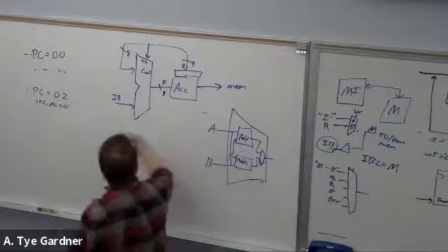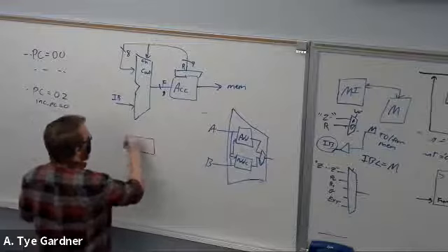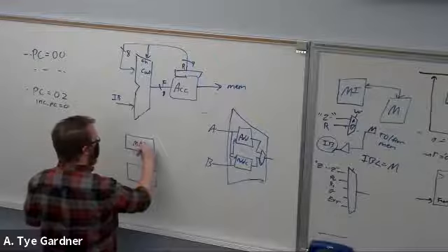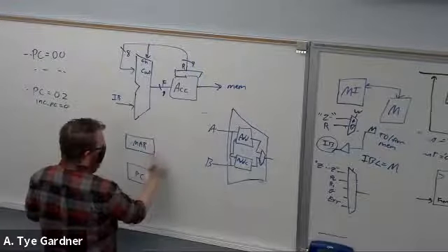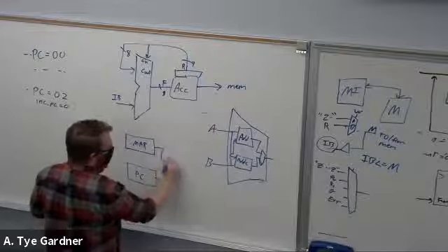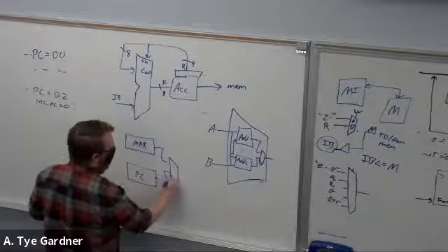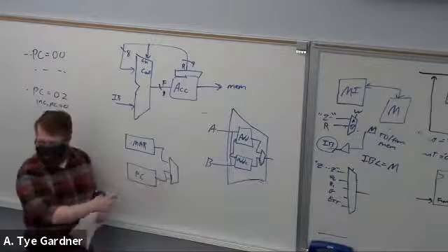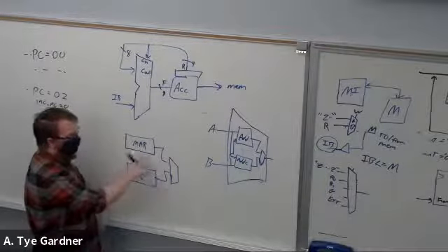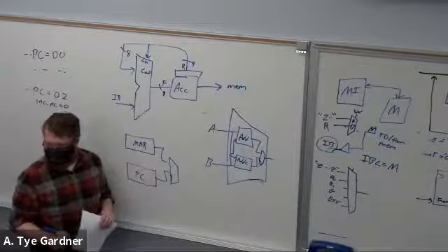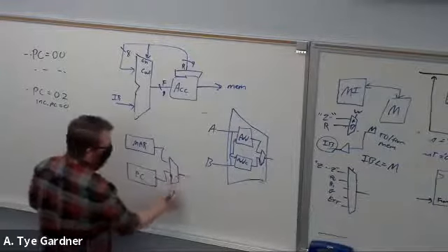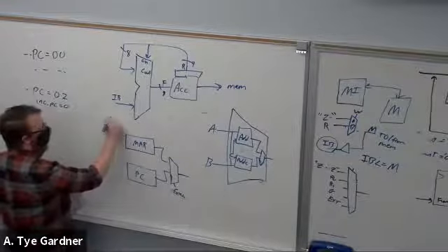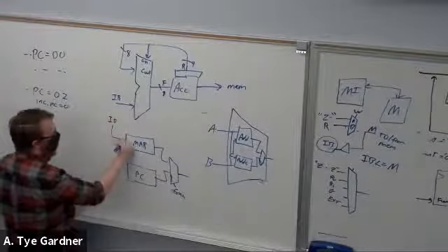Okay, so then the last bit that is pretty confusing is the PC and MAR. And again, we have a mux. I've seen too many students trying to write a whole new mux that has inputs called MAR and PC. Don't do that. Make ports A and B that map to MAR out and PC out, right? And then we have like this thing called fetch. Okay. And then here, once again, we have the internal bus.